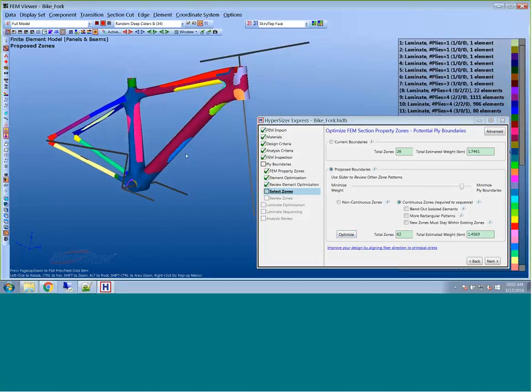Then after that, we just select these zones and size these zones, and that's the part you have already seen with the torsional stiffener Craig presented. You have the exact same capabilities later on, where you can see the stacking and so on for each and every ply, for each and every patch, for each direction that we have.